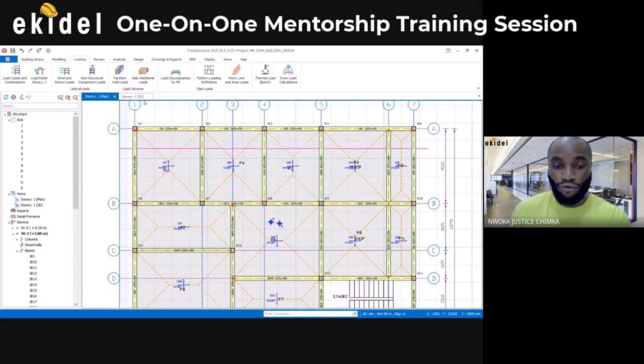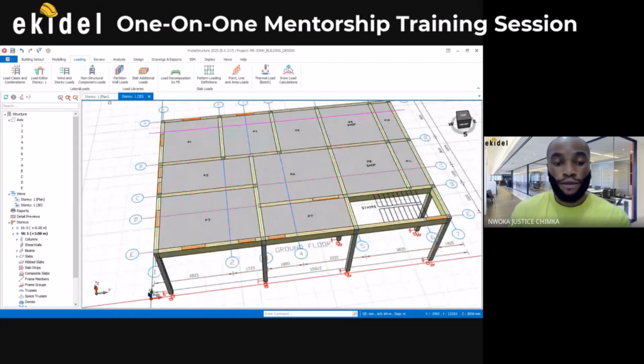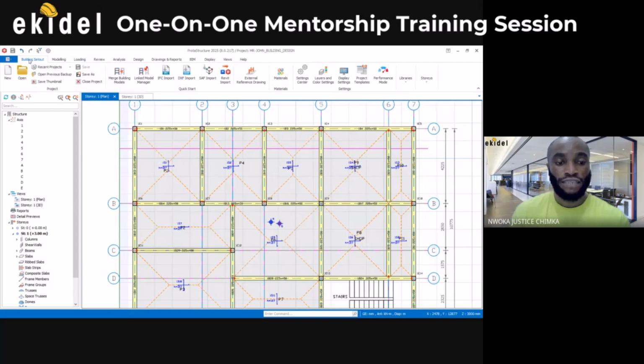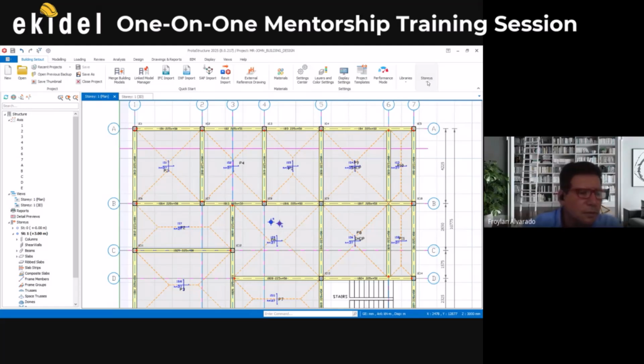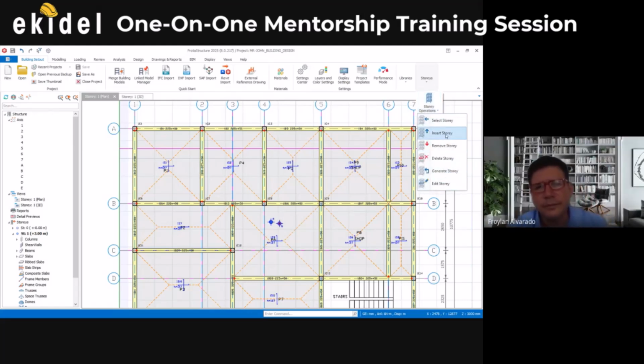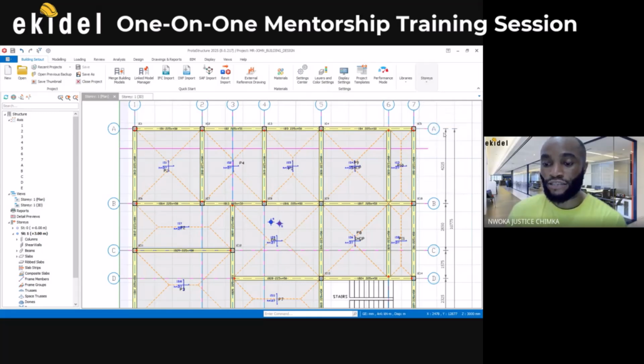So with that, you have done the hinging. Next thing is to insert story. To do that, we come under the building setout tab, then you see the option that says Stories. Click on Stories, you see story operation, click on this, and then you see insert story. So I'll click on insert story here.